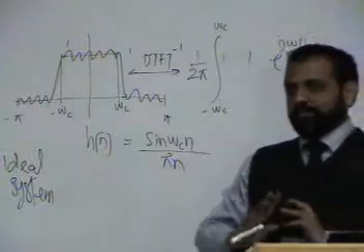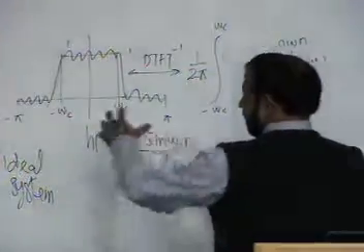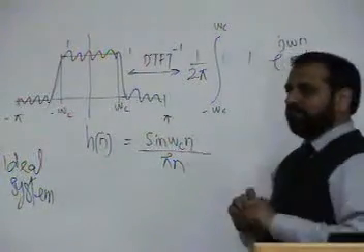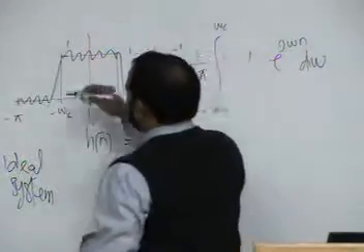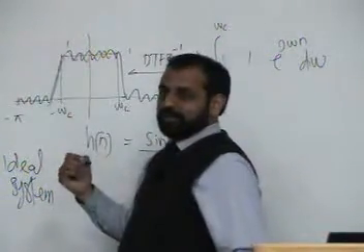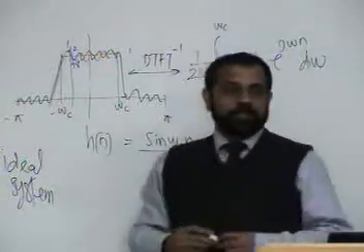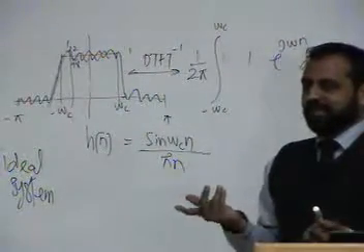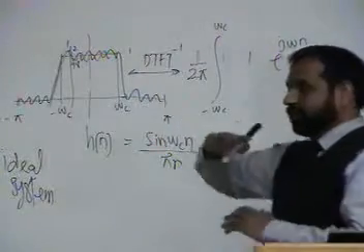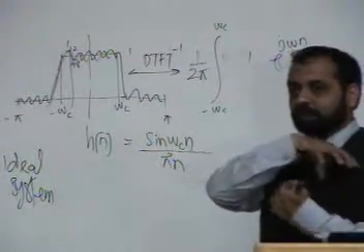So all the DSP we are going to study in the first part of this course will try to get you closer and closer to an ideal system, a realizable system which gets you closer to ideal, but you will always have transition and you will always have ripples. What will a ripple do to your wanted frequency? If it is 1.2 and this is 0.98, it means this particular frequency content will be multiplied by not 1 but 1.2, so it will be amplified a little bit. What about 0.98? It will attenuate it.